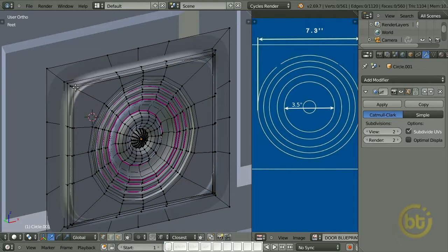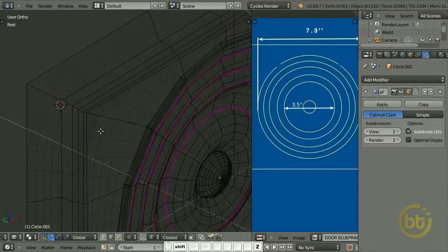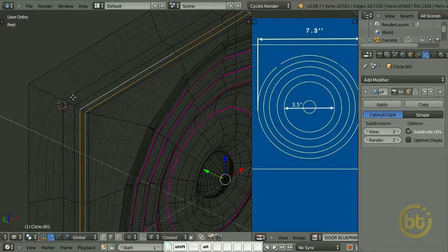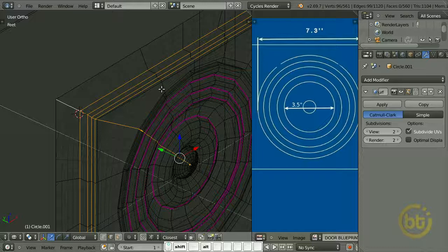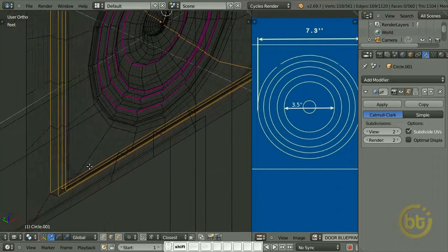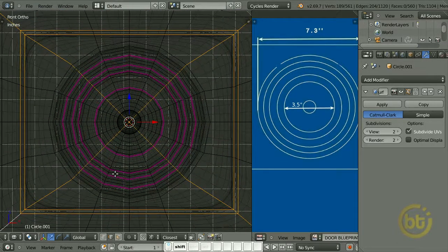Okay. Now press Ctrl Tab to go to the edge selection mode. Go to the wireframe mode. Select these edge loops by holding Alt Shift and right click to select those edges. This one, this one, this one, and finally this edge loop. Okay. Go to the front view. Press C for circle selection tool. You can increase or decrease the size of circle by using your middle mouse button. Scroll up or scroll down like this and deselect these edges.